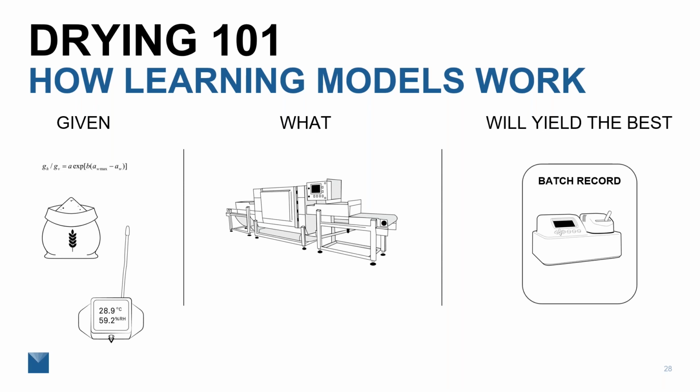For example, a manufacturer of meat snacks that are smoked in a batch oven recently implemented our Scala IoT system on its manufacturing floor. The system started with a model based on the physics of drying food, and then used meat thickness, oven wet bulb, oven dry bulb, and meat internal temperature as model inputs. Each time the drying process was completed, the machine learning model in Scala had a predicted water activity and moisture content for that batch. Technicians then measured batch samples for water activity and compared predicted to actual moisture levels.